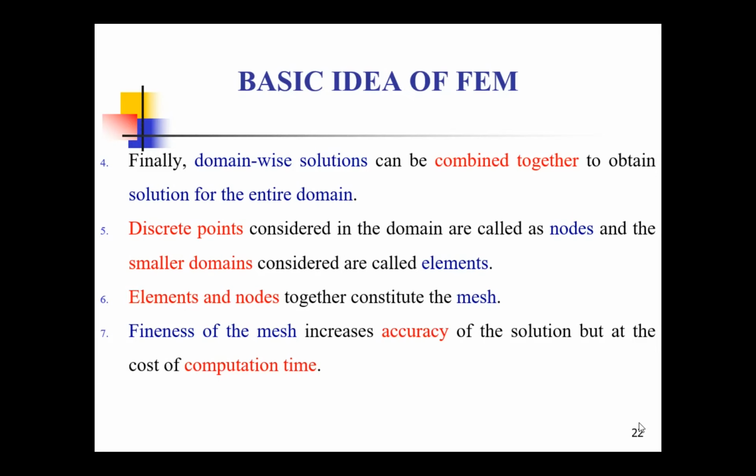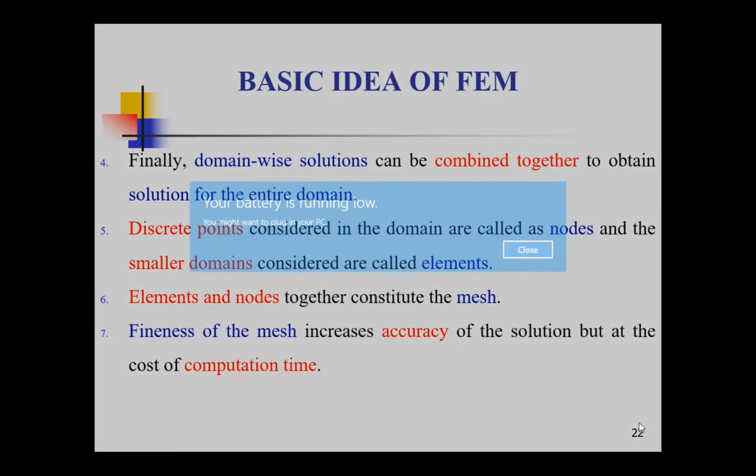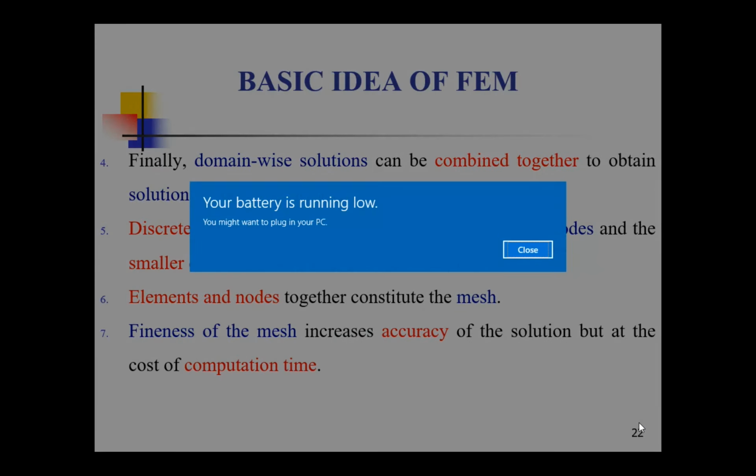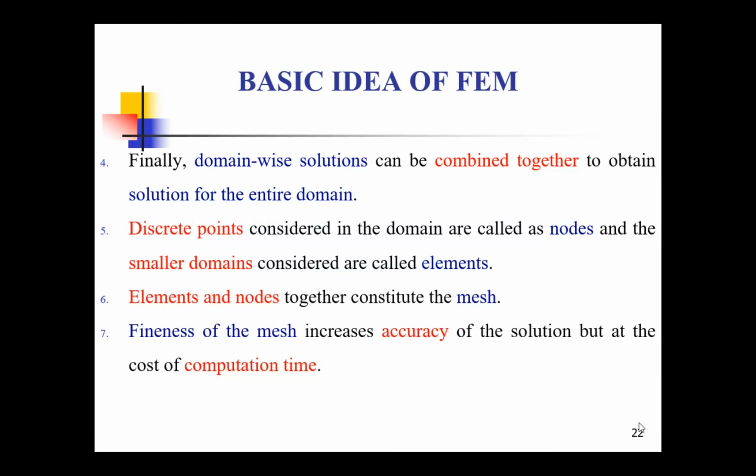On the contrary, if I consider only 100 elements for the particular part, that means I am going to consider coarse elements, that is bigger elements. So 1000 is fine elements, 100 becomes coarse. Obviously, results will not be that accurate, but the computational time will be lower.